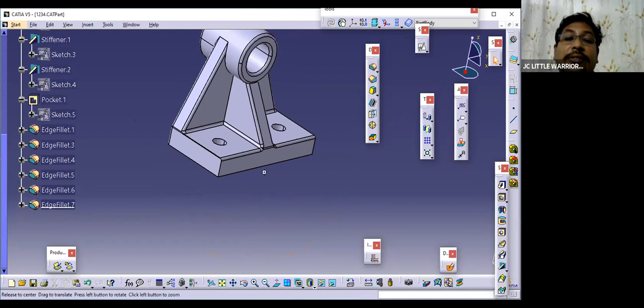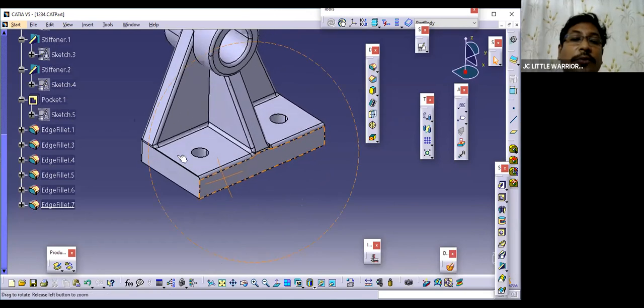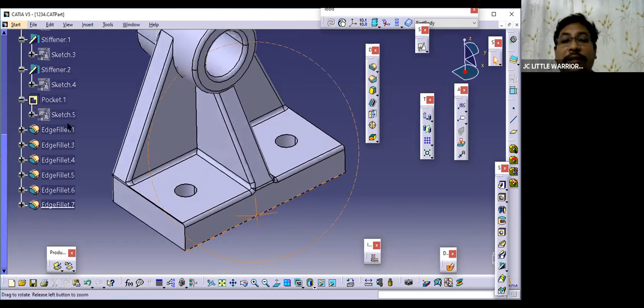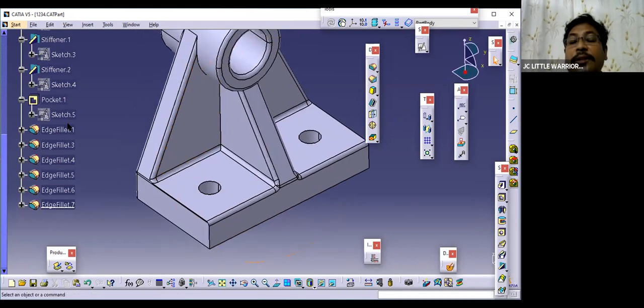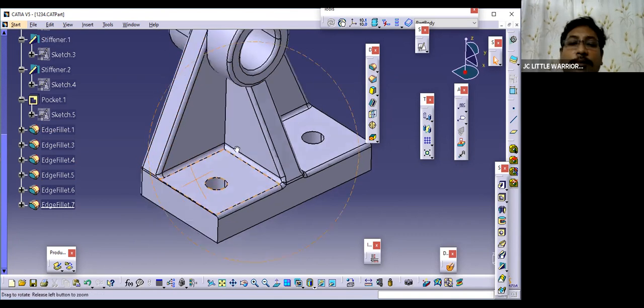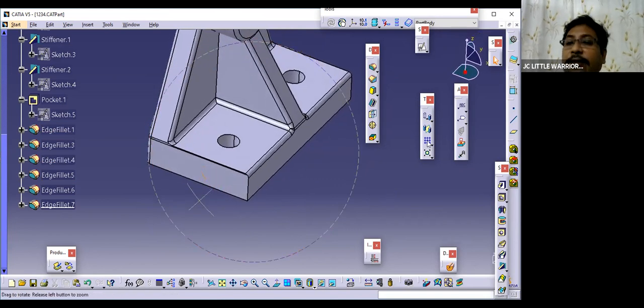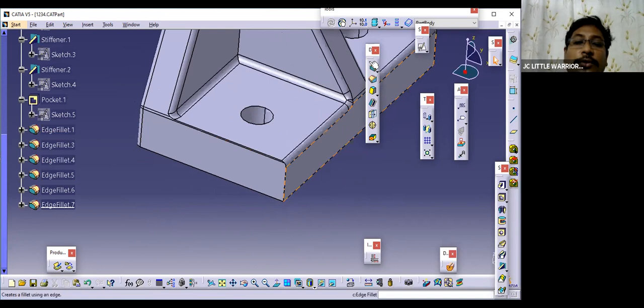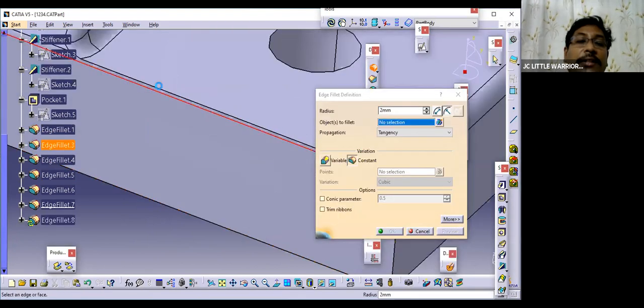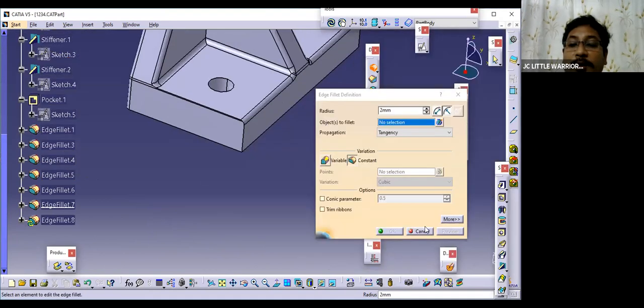So it distributes the stress over a broader area, smoothly. If the area is very sharp, it's very easy to fail in that area. If the part has sharp edges, stress is not going to be smoothly distributed, and that's the reason there are chances of failure. Maybe in this drawing it is not shown, but this is how we have to give it.